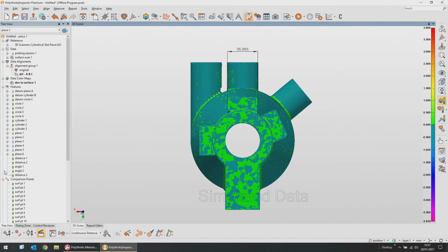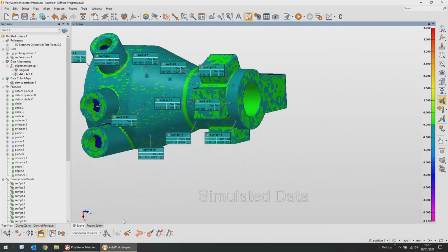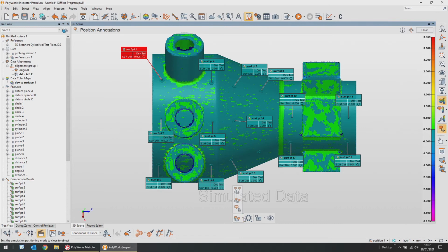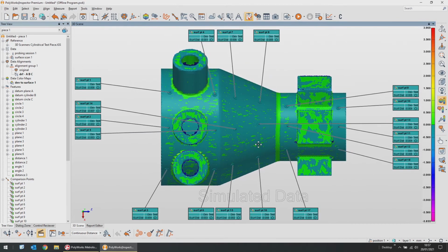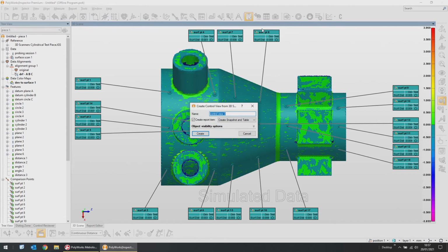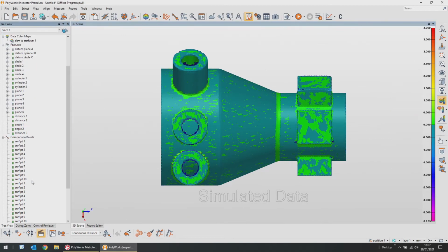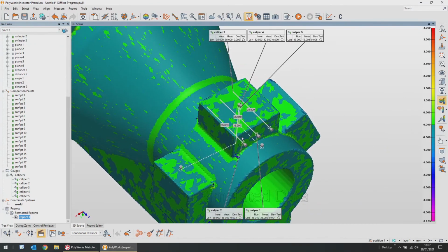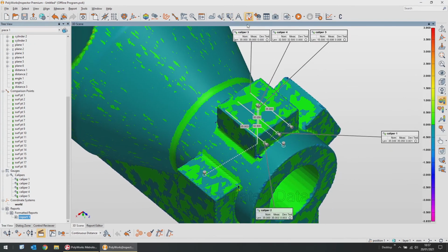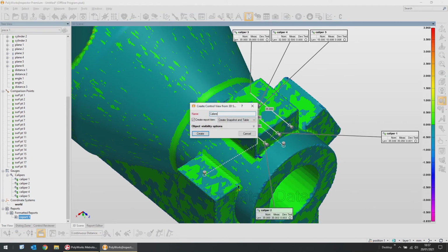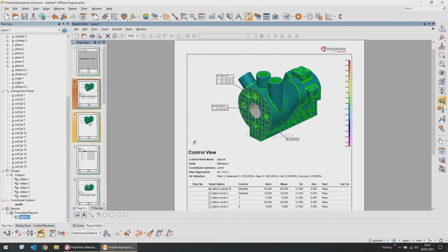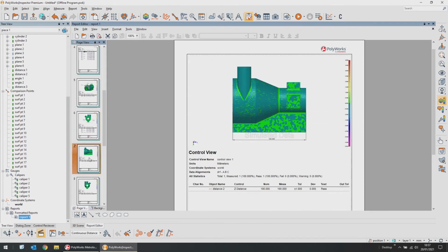And obviously I can do the same for my comparison points. And in this example, I'll just get PolyWorks to spread them out. And again, create both a snapshot and table at the same time. So comp points. And even for my calipers as well. Let's do that view there. Calipers. Okay, so everything is now reported. Snapshots, tables for each of those areas.